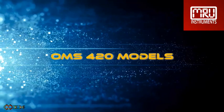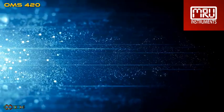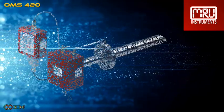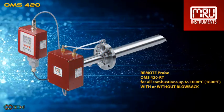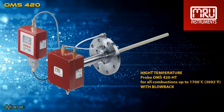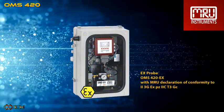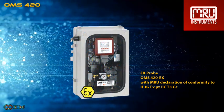Let's have a look at the available OMS 420 models. The OMS 420 Compact, for clean flue gas only. The OMS 420 RT, remote, for all combustions up to 1000 degrees Celsius, available with or without blowback system. The OMS 420 HT, high temperature, for all combustions up to 1700 degrees Celsius with blowback system. The OMS 420 EX, with MRU declaration of conformity to EX Zone 2.